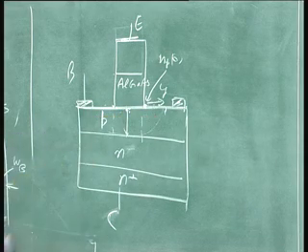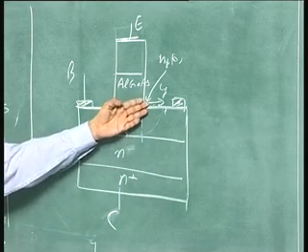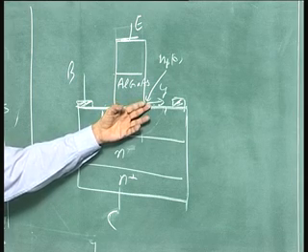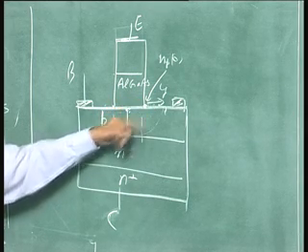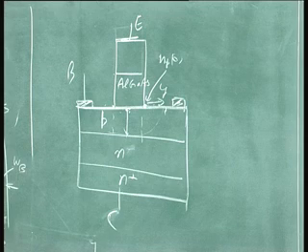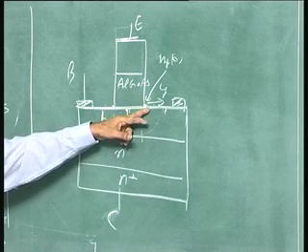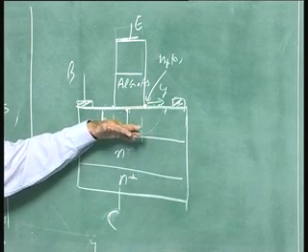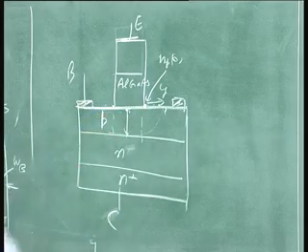So, any deviation from periodicity acts as a deep level, and as I pointed out in the case of Schottky barrier, these recombination centers are distributed all over the surface, all over the energy band diagram. So, how do you reduce the recombination velocity?